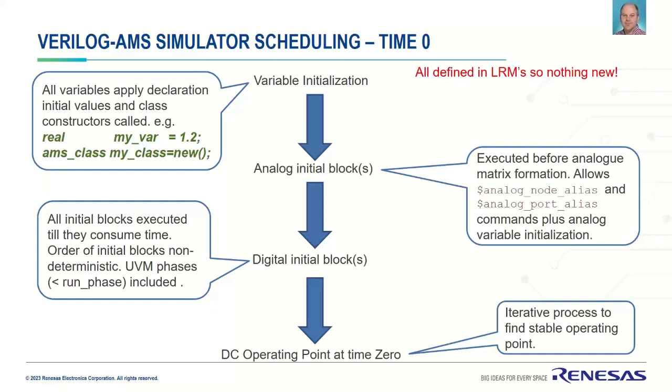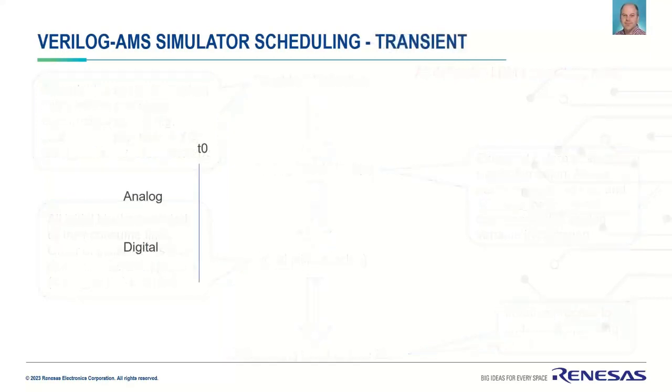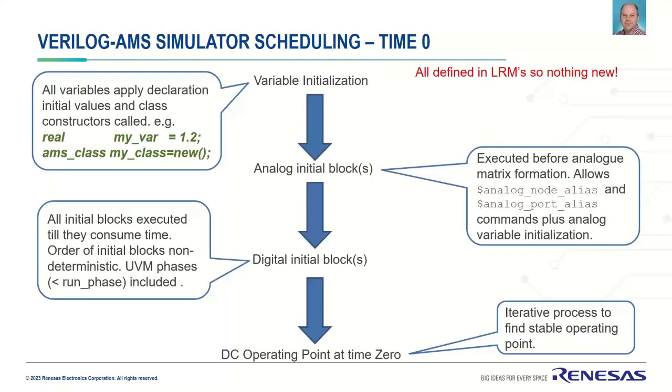You look worried, Andrew, but most people don't actually do that. No, they don't. Is that a safe thing to do if many of your nets are not initialized? Sometimes in digital the nets that go to the analog are not initialized at time 0, or they're X. Your connect module will probably convert that, and if it's got a voltage supply that's 0, that X will go to 0. So yeah, okay, you're safe.